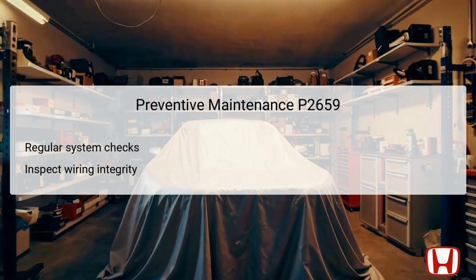Preventive maintenance is an important aspect of vehicle ownership that can help avoid DTCs like P2659 in the future. Routine inspections of the rocker arm oil control solenoid and its associated wiring should be part of regular vehicle maintenance. Checking wiring harnesses for signs of wear, fraying, or corrosion at connection points is essential to maintaining electrical integrity. Regularly monitoring fluid levels, especially oil, also ensures that the VVT system operates optimally.